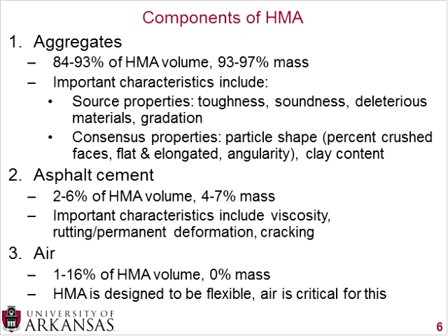Whereas consensus properties consist of particle shape, which includes percent crushed faces, flat and elongated, and angularity, both coarse and fine aggregate angularity, and then also your clay content. Now, you'll note that in general, source properties are things that you really can't change. That depends on where it comes from. Some people do argue that you can change the gradation of aggregates by different crushing techniques and such, but after extracting and crushing, those source properties can't change.